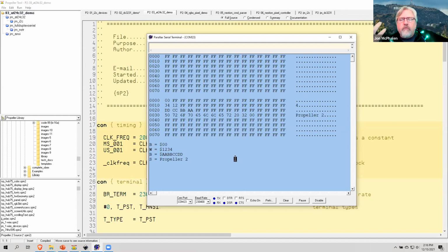If you have a new product, say, and you want to know if things have been initialized, your program can assume there should be a non-FF value in a specific spot in the EEPROM. When you start up, you look for that. And if it's FF, then you know it hasn't been initialized and you can set it up.